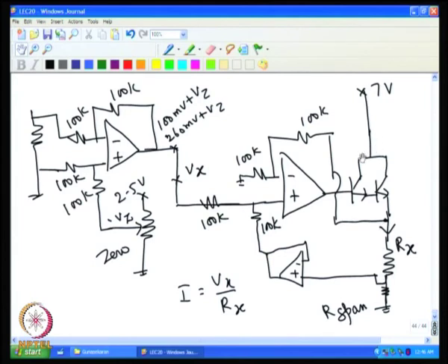That means this current plus all the rest of the current put together should not take more than 4 milliampere, maybe about a milliampere current can be taken. That means at this voltage level we need 1 milliampere current, and at this voltage level we need around 17 milliampere current, assuming 3 milliampere is drawn by other circuits.